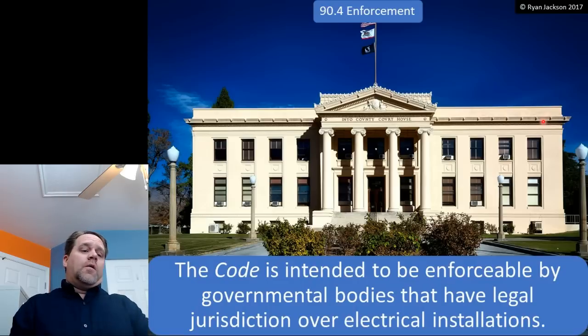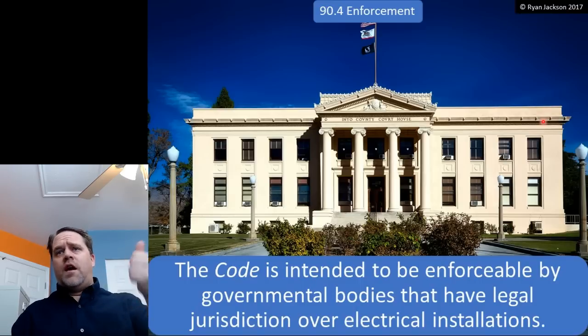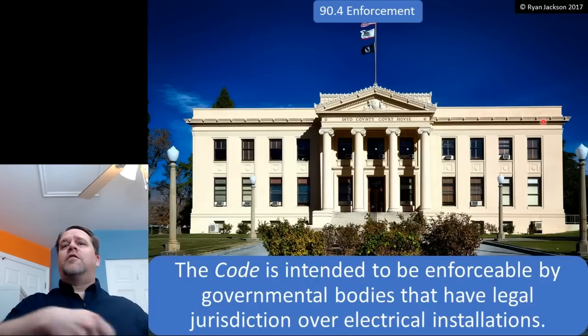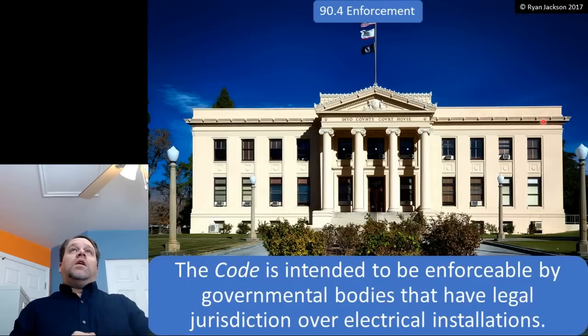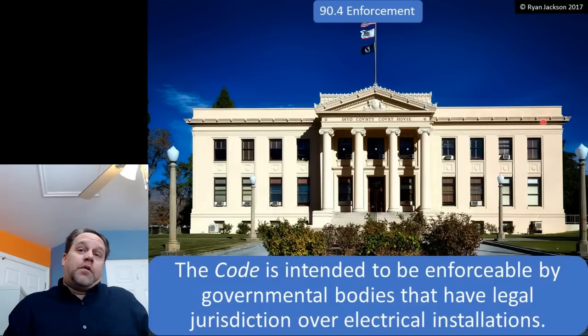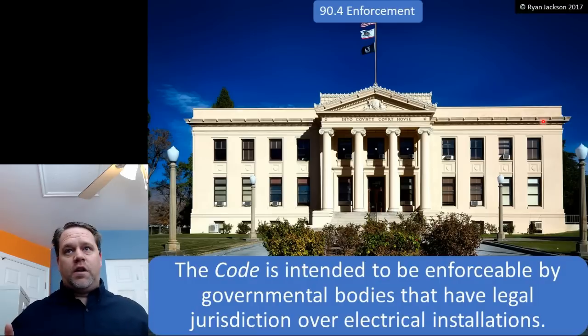In fact, you go to Chicago, most of Chapter 3 does not exist in Chicago. You can't use cable wiring methods. So AC cable, MC cable, NM cable, UF, SE, all that stuff, rip it out of your code book, and that's the Chicago code. Right? In Utah, we took out AFCIs, which I personally don't agree with, but it is what it is. So they took AFCIs completely out of the code in Utah, and then they adopted it. You can adopt the code however you want to adopt the code. So it's not a federal law or anything else. It's just however it's adopted, that's how it's adopted.